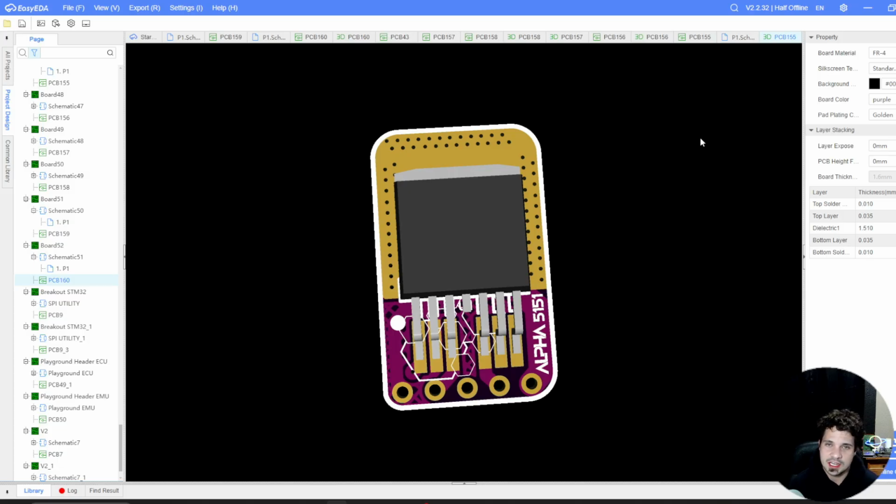So when we look at a VTEC solenoid that was originally drawing potentially 0.8 amps of current, when you factor in the age of it, the wear of it, and modified wiring or oil from the engine on the wiring, you can actually experience much higher amp draw than 0.8 amps. And the original SI5151 used on IC14 in the ECU is actually rated for almost 2 amps. It's rated at 1.8 amps.